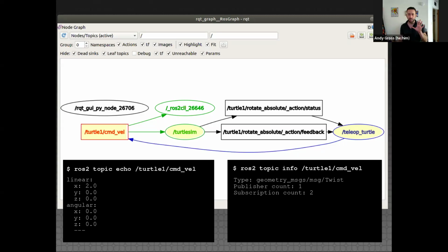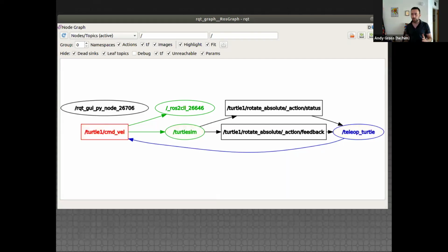And this is where I really want everyone to take a moment and see if all of this is starting to come together. Because in order to send information between the input device, which is a node called teleop turtle, and turtlesim, we are essentially just writing text to basically a human readable text file in a standard format, and then having a downstream node read that in, right? That is the basis of ROS, and it almost sounds stupid. Like, it feels too simple. You're like, how is that the big innovation? But no, seriously, if you think back to all the stuff that we discussed at last month's meeting about how do we create standards, how do we make interoperability, this is basically it, a framework of communication with standard formats. So from there, we can go further. I need to get to the next slide.